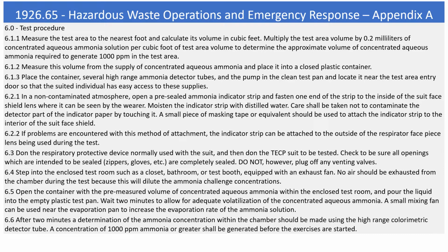6.3. Don the respiratory protective device normally used with the suit, and then don the TECP suit to be tested. Check to be sure all openings which are intended to be sealed, zippers, gloves, etc., are completely sealed. Do not, however, plug off any venting valves.